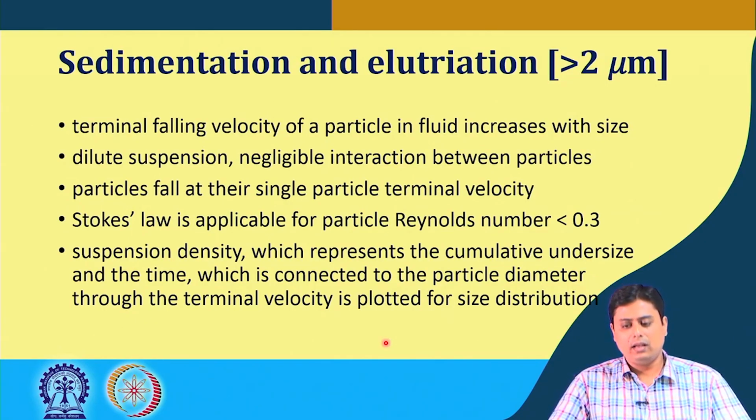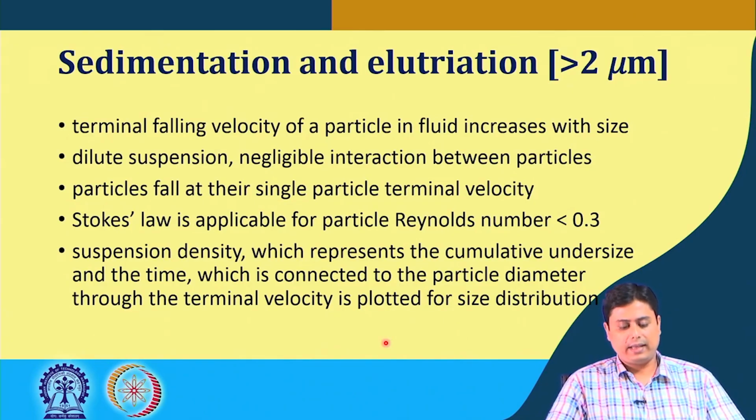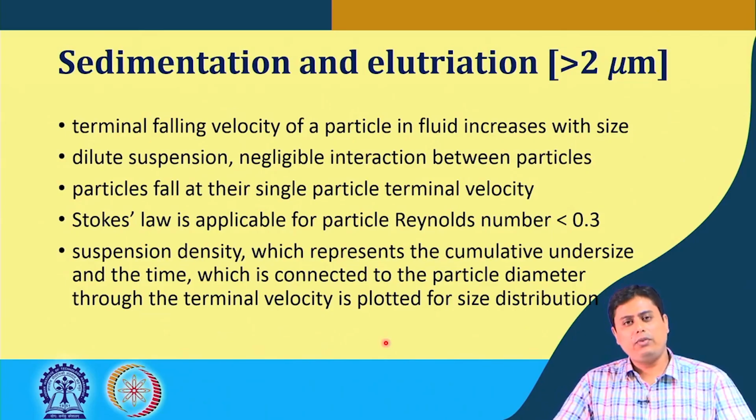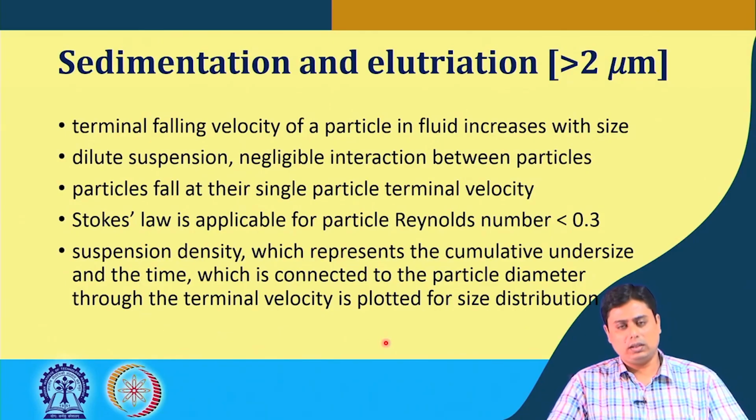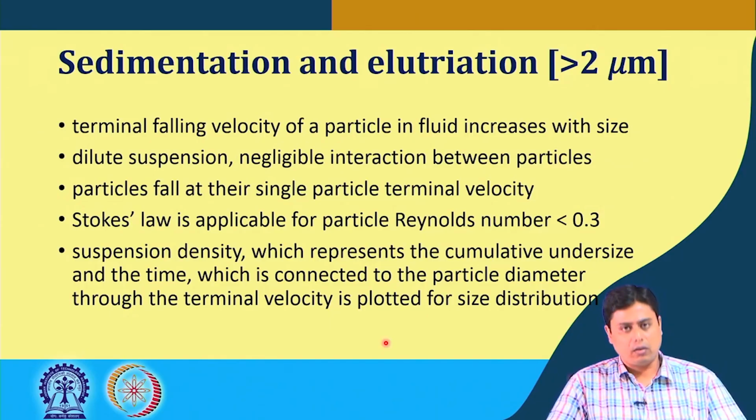By this technique typically 2 micron particles can be separated, but if we apply Stokes law in water, the calculation shows that particle sizes of 50 microns and larger are easily determined by this when the fluid is water.